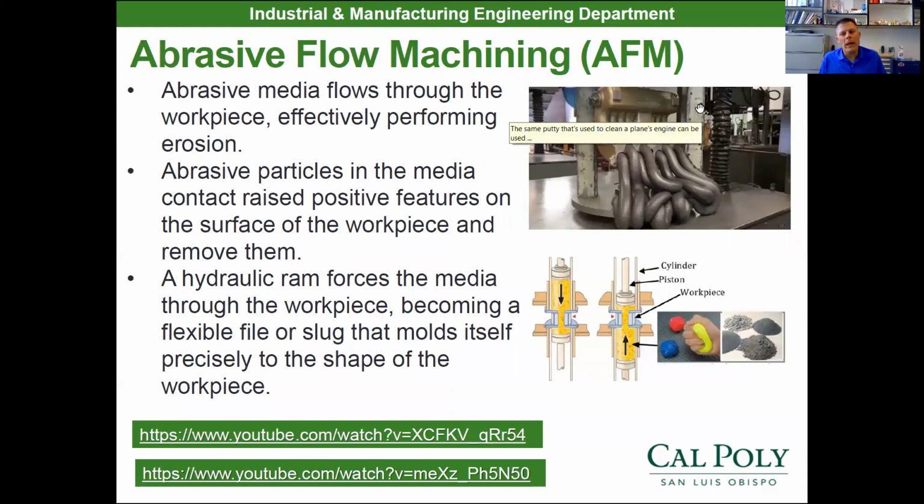Now, honing was for holes or circles, right? Or bores. So if you didn't have a perfectly shaped bore and you wanted to abrasive deburr the inside of a port, you could do abrasive flow machining. This one's really cool. This process is like you took Play-Doh to the beach and dropped your Play-Doh in the sand and it got a bunch of sand in it. Then you take your Play-Doh with a bunch of sand in it and force it through a port.